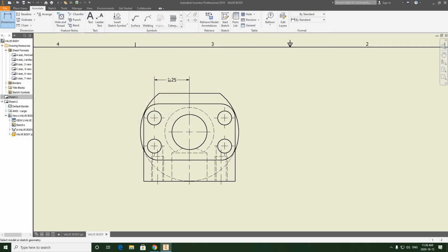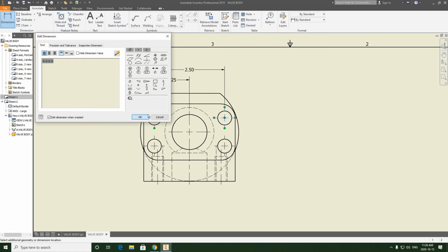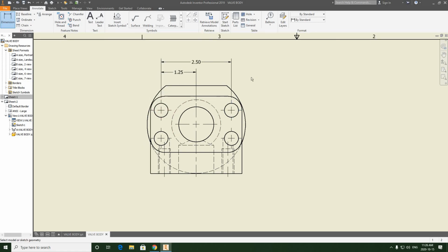Now this dimension is shown between the views in the other handout that I used to draw this, but again, I'm making some minor adjustments, trying to keep things from between views when I can, right? We try to keep dimensions outside of views if possible. We only put them between when there's an actual advantage to do so. So there's going to be our 2.5. That's in the same position.